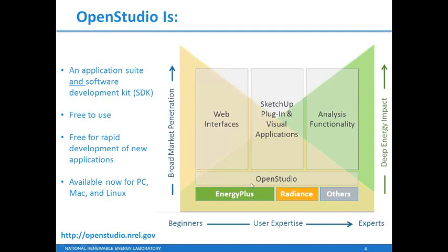OpenStudio is kind of a core software development kit. OpenStudio gets thrown around a lot. Some people thought it meant the Sketchup plugin, but it's now this larger development project which has a core, and then it has interfaces that sit on top of it, and they're all part of OpenStudio. One thing OpenStudio is not is a simulation engine. It passes off your model to originally Energy Plus, and now additionally to Radiance, and we are working on support for other simulation engines as well.